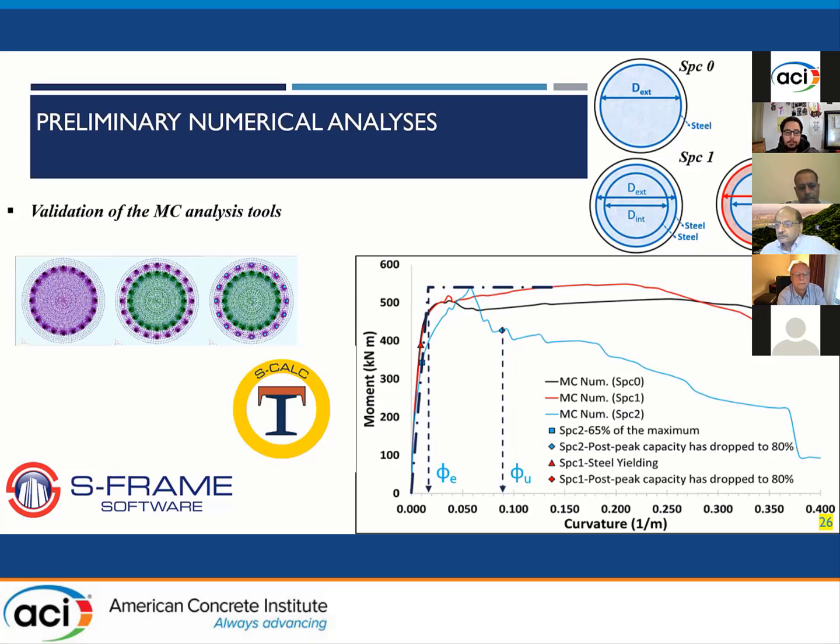You can see here the moment-curvature analysis and how we defined the end of the elastic phase for FRP and the ultimate value. From the ultimate value over the end of the elastic, or inelastic, deformations or curvature, we can define the ductility of the section.